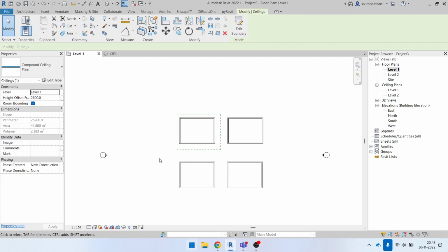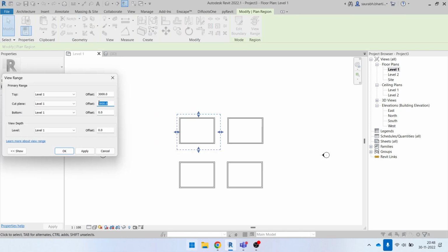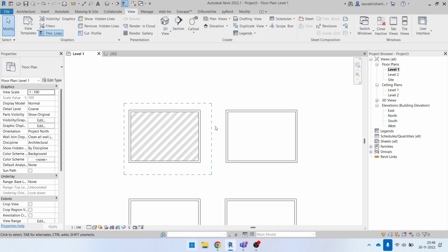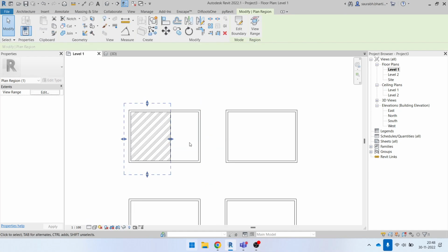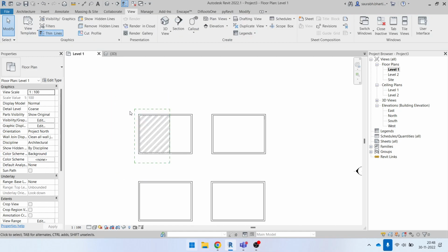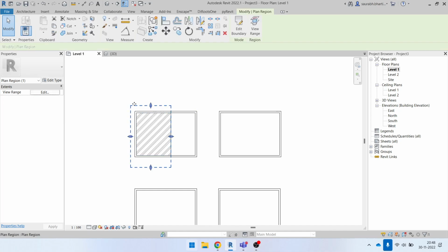If I go to the plan view, here our view range is 2600, let me go to 2700 and let's see if I can see that. Yeah, as you can see, our ceiling starts at 2600 mm. So this is what I wanted to do earlier actually. As you can see in the view range here, our ceiling would only be visible if it is within the view range.